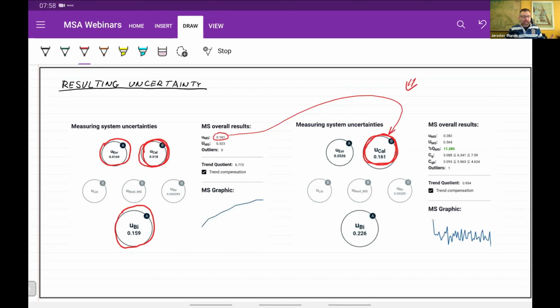And what would we do next? We would do the standard type 2 study, which will land us exactly at measurement process uncertainty. This trick can be used not just in leakage, but in many cases where we have some master and we relate the exact value to that master, not only in absolute measurements, but also in relative measurements.